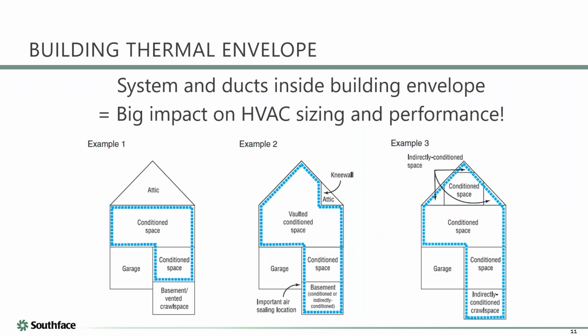Also, the choice of how we define the thermal envelope for these three identical houses can have a big impact on the load, and whatever affects the load, of course, affects the operational costs and performance. We can put a duct system in this place, and in some of these designs it's in an attic, and in some of these designs it's inside the thermal envelope. And when I say duct system, I mean the equipment as well. Same for down here.